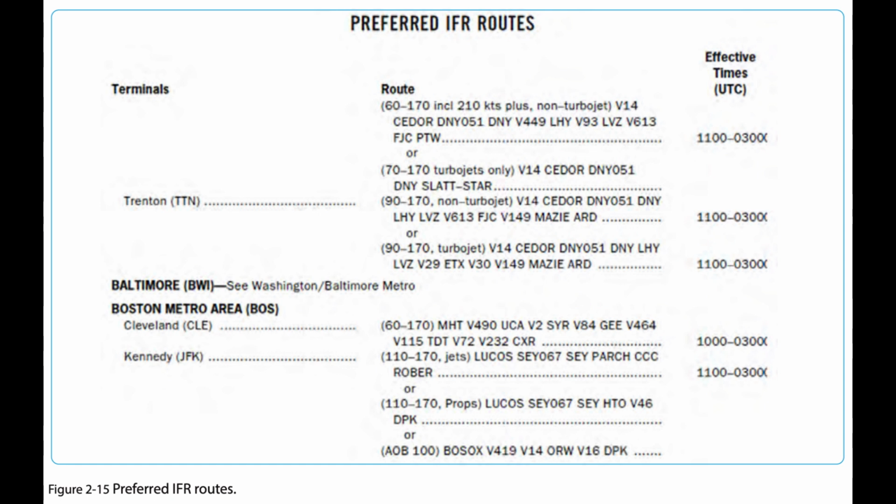Substitute airway or route structures. ARTCCs are responsible for specifying essential substitute airway or route segments, subroutes, and fixes for use during scheduled or unscheduled VOR/VORTAC shutdowns. Scheduled shutdowns of navigational facilities require planning and coordination to ensure an uninterrupted flow of air traffic. Aeronautical Information Services, in coordination with the ARTCCs, determine when the length of outages or other factors require publication of subroutes. Flight Program Operations, AJW3, provides flight inspection services, obstacle clearance verification, certification, and final approval of substitute routes.